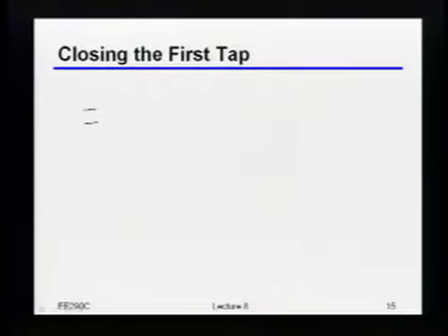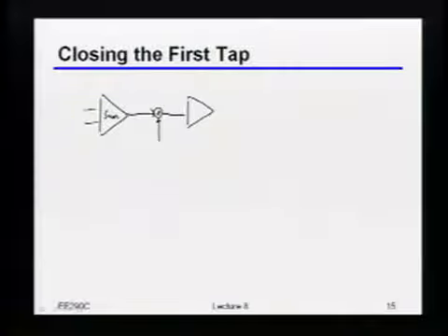Okay, and so to highlight why that is, let's draw a little block diagram of what this thing looks like. So the DFE, I usually go into some summing amplifier. Right, then again in the current domain, I'm going to subtract off whatever that ISI is. I will still tend to go through a preamp before I go into the comparator.